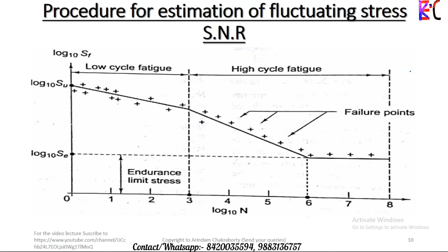In another way around, it is very impossible for engineers to understand the complete entire body, whether this part is working or not, and to gather all the data. So they can check the SN curve of the parts of the object. They could actually get an idea whether the part's life cycle has ended or not. They could understand over here.